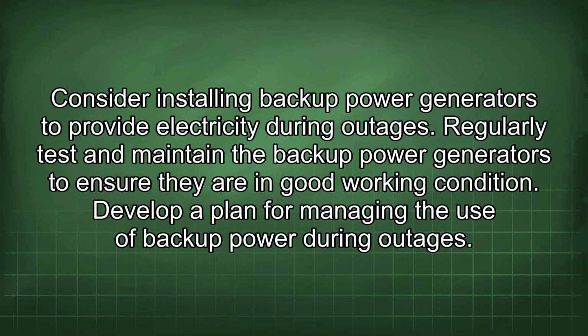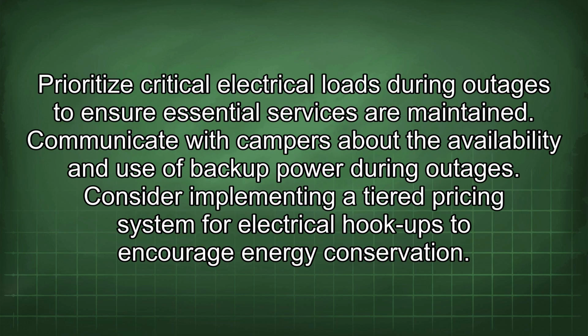Regularly test and maintain the backup power generators to ensure they are in good working condition. Develop a plan for managing the use of backup power during outages. Prioritize critical electrical loads during outages to ensure essential services are maintained. Communicate with campers about the availability and use of backup power during outages.